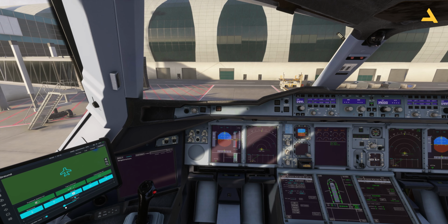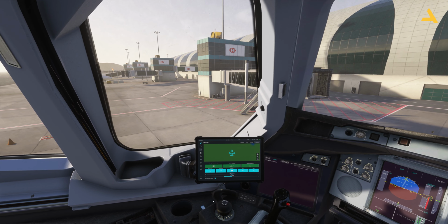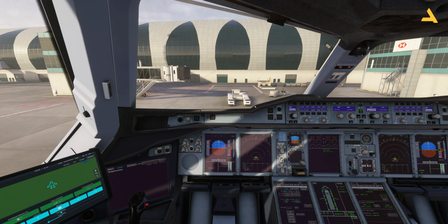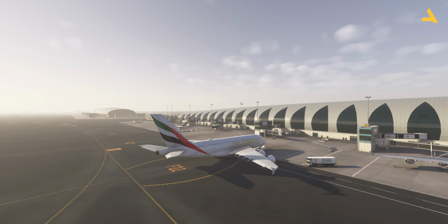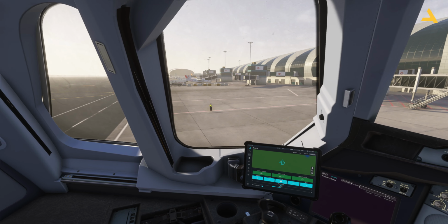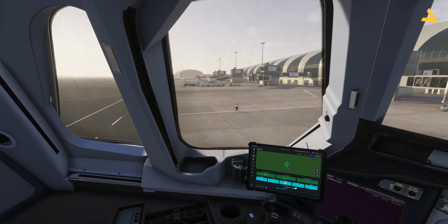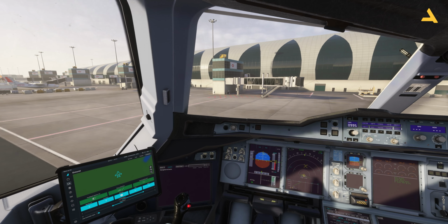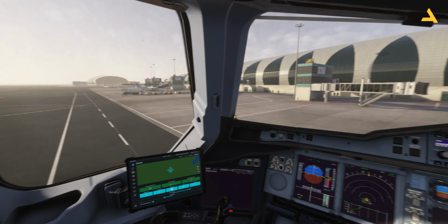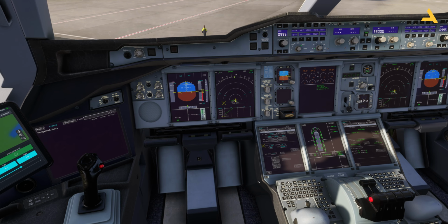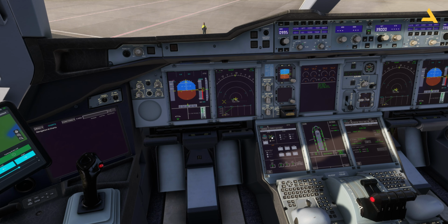I can further increase the speed. And from here I can also change the direction, whether to turn left or right. The tug is there. Is anything? Yeah, now it's back again. So let's turn right. With this, I can also turn on the transponder. If you go over here on the screen, you will see this option, squawk, and set it to auto and TA/RA. That's it.